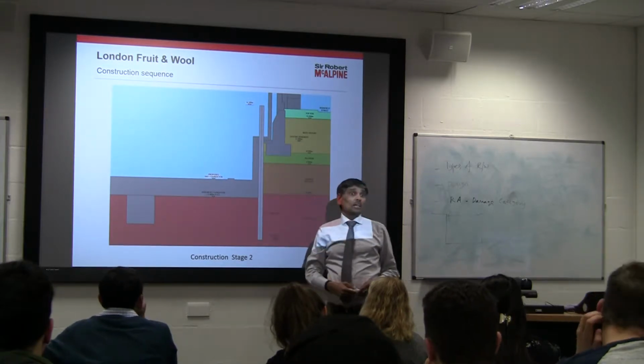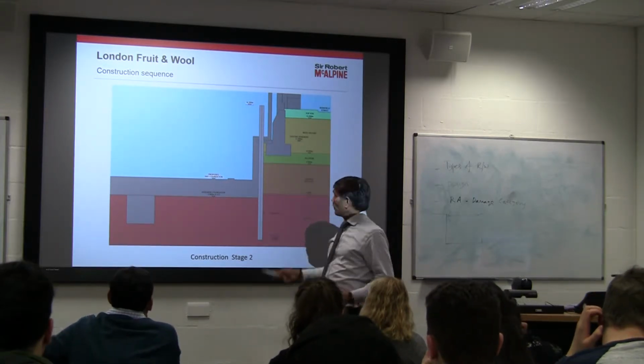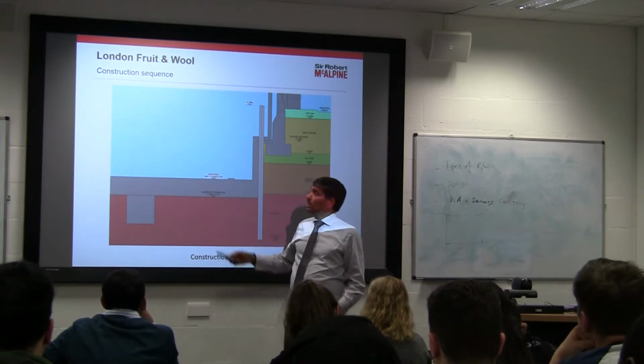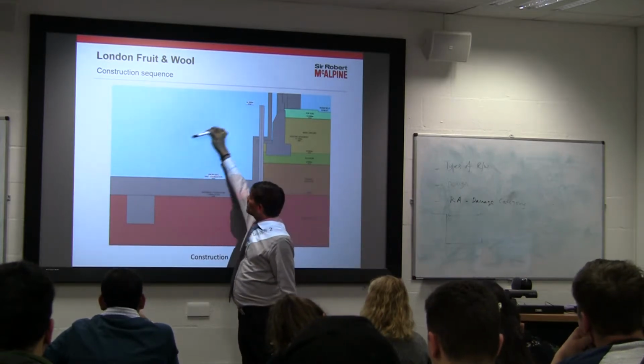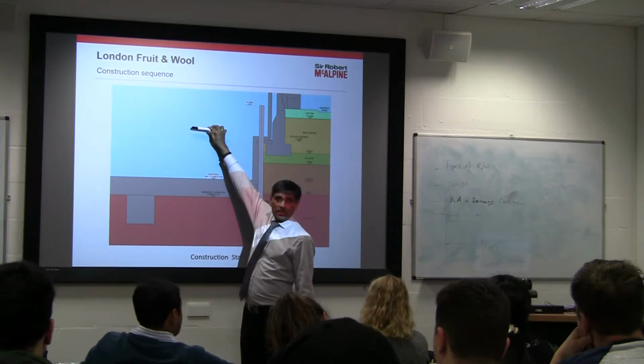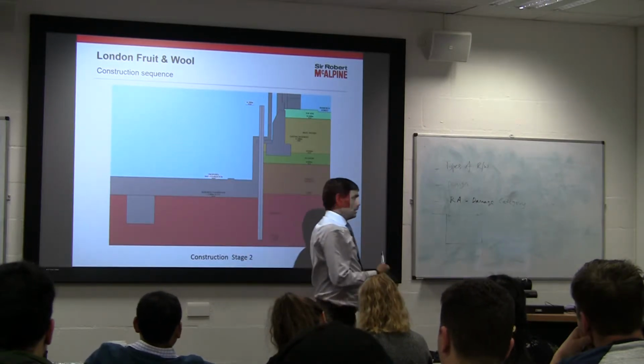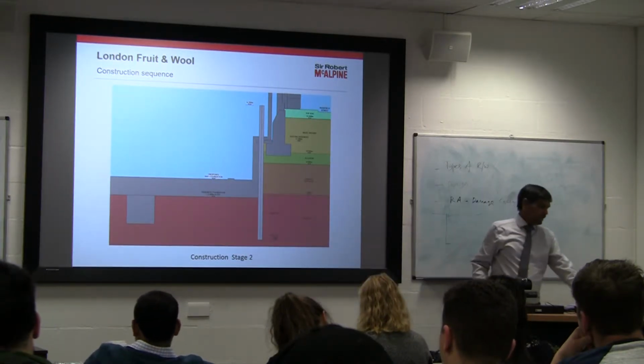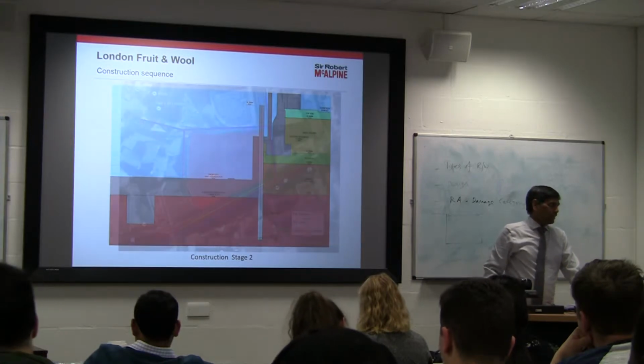So again you've got to think about at what stage I should remove it, because that prop, as I said, is about 7 or 8 tons. You need to detach this and you need to lift it out to build all the things that are going in the basement. So that's another sequence. So again you've got to think of the removal sequence.